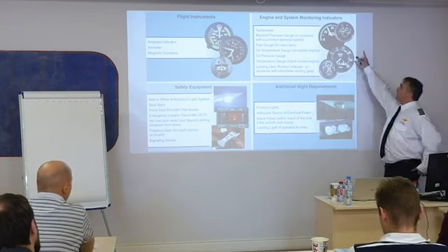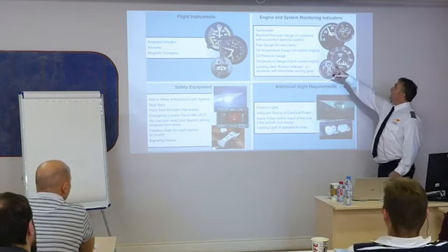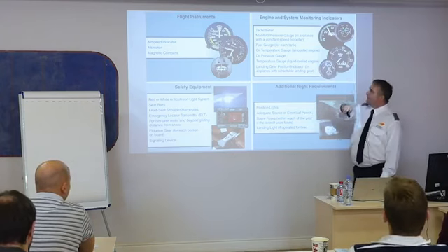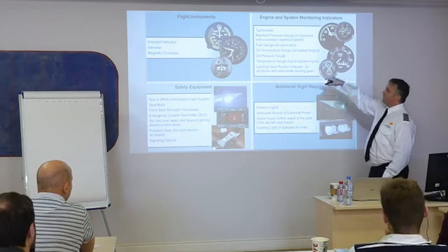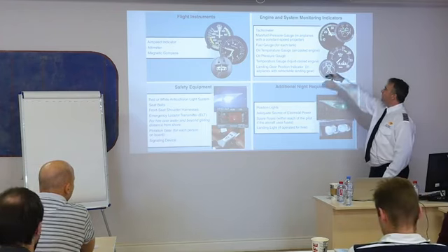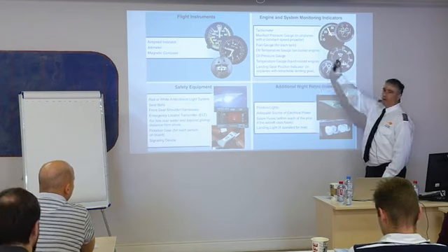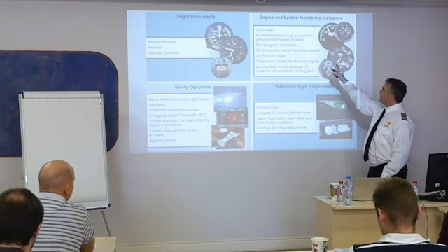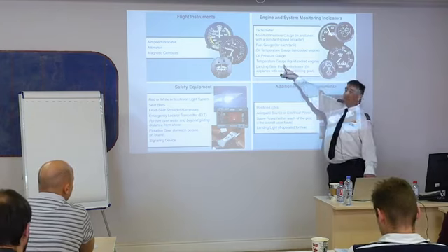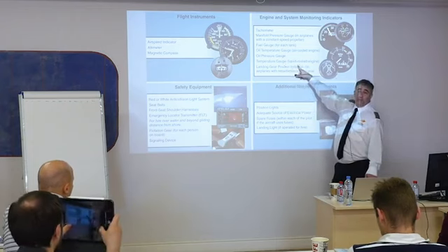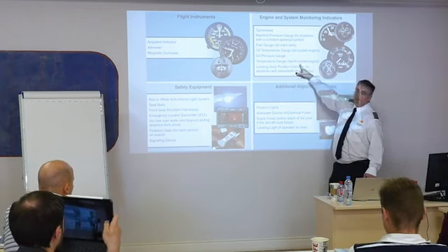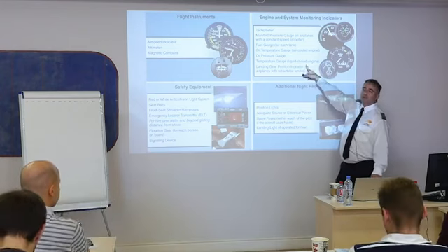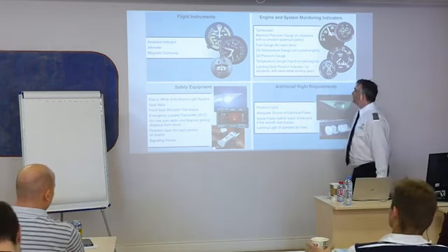Engine and instrument monitoring indicators. There's all kind of stuff. Look at all the stuff I need. Tachometer, manifold pressure gauge if I have a constant speed propeller, fuel gauge for each tank, oil temperature gauge, or oil pressure gauge, a temperature gauge. Remember I said some airplanes have liquid cooled? We have one of those. Well, you guys don't need this in the training airplane, but we need this in that airplane.